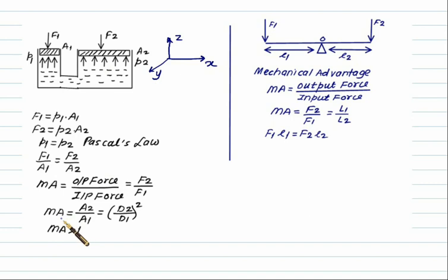Remember here that the pressure is given by rho gh, so the height is restricted; it is not applicable for long columns. Suppose I change the height of this vessel and shift the ram to this position, and say this height is very large, let's say 2 meters. In that case, we must have a relation between P1 and P2. This time P1 and P2 will not be the same. They will be different values because pressure will change. From this reference, this is at a higher point, so pressure is going to decrease.